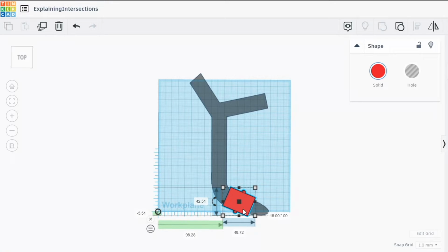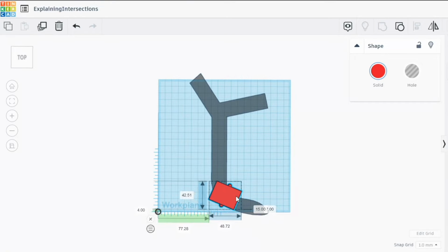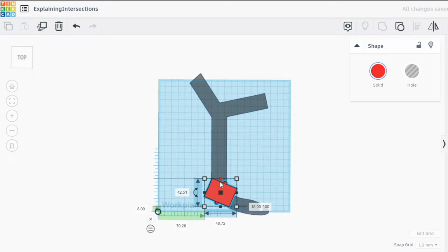So at the beginning of our motion, both the sensors detect white light as they face the ground. It keeps moving in a straight line. And as the object moves and arrives at a turn, this sensor faces black light, whereas this sensor faces white. So according to our logic, this side stops moving, whereas this side keeps moving.